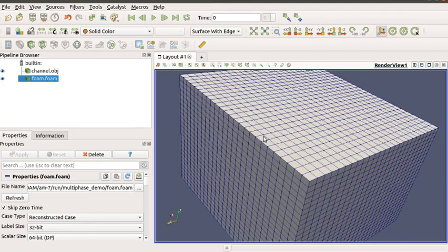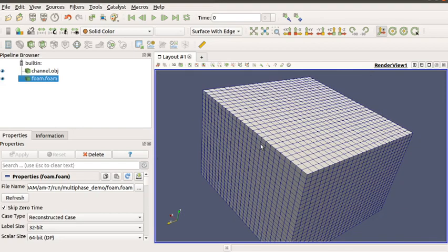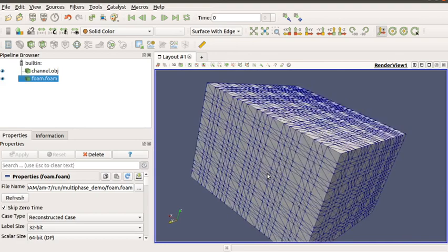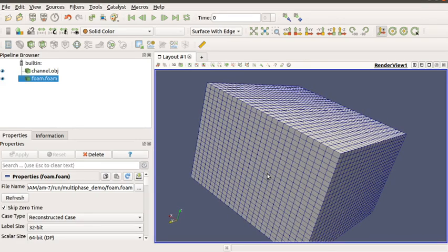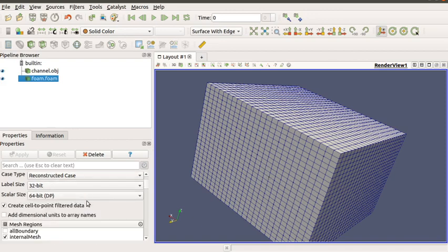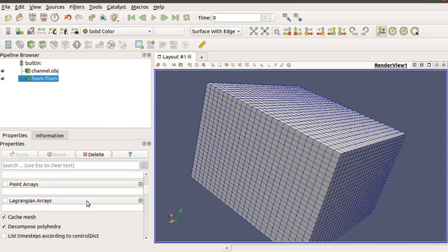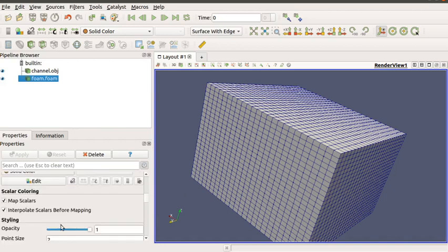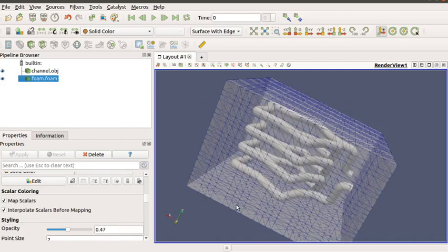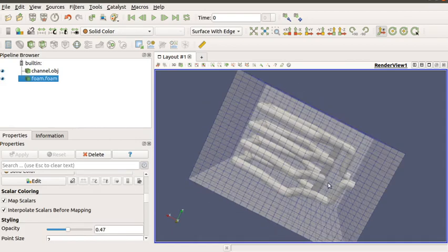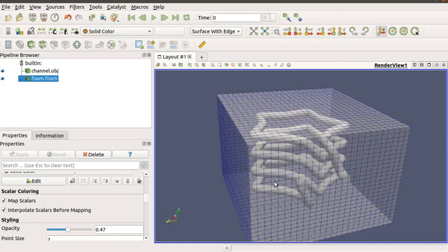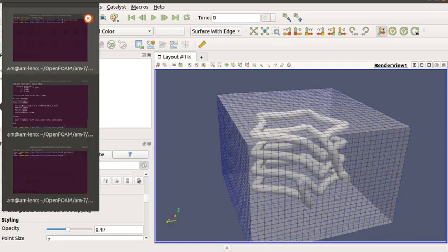Within this blockMesh, our geometry should be contained. It should not fall along the face, or go out of this blockMesh. It should be well within the boundary mesh. If I make this boundary mesh transparent, you can see our geometry, that is a conformal channel, lies within the boundary mesh. So this step is okay.